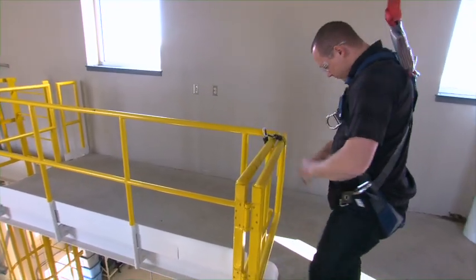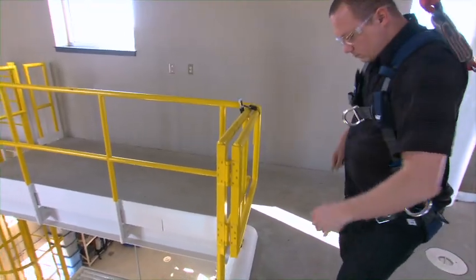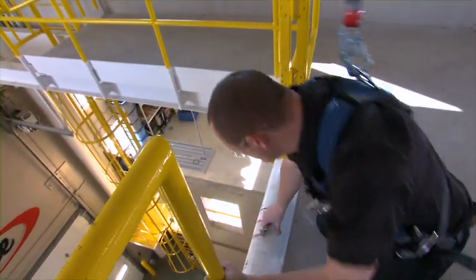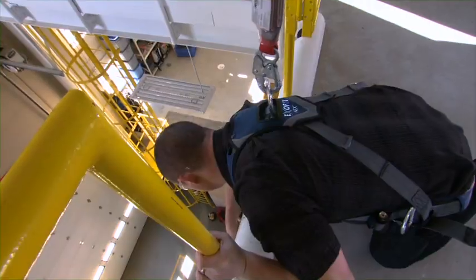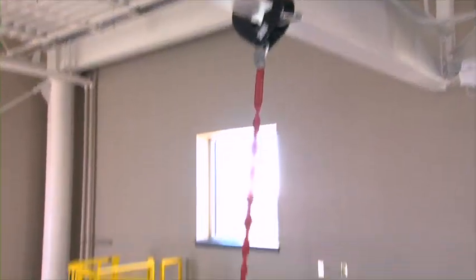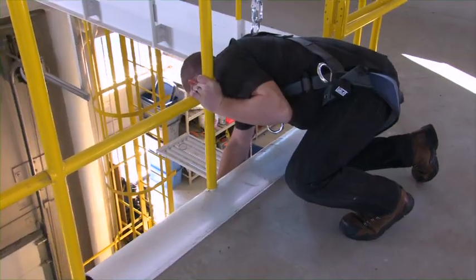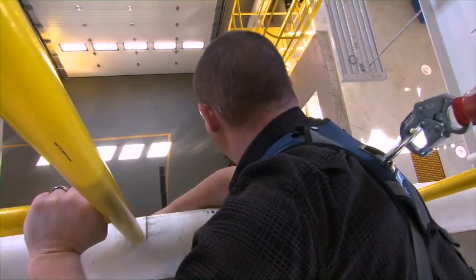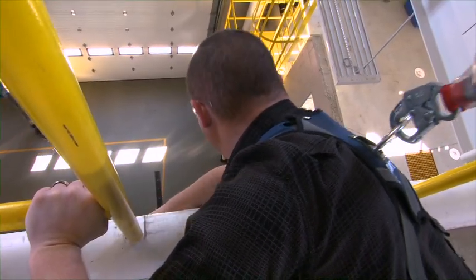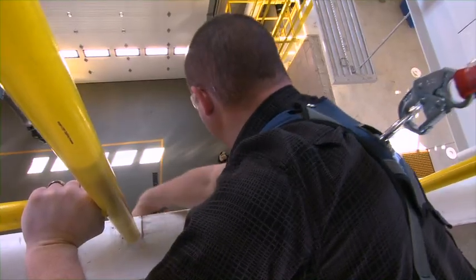Personal fall arrest harnesses have a maximum weight capacity defined by the manufacturer, which includes the person and tools. If there is a need to use a personal fall arrest harness for someone outside the stated capacity, then your employer will need to contact the manufacturer and request a suitable harness. It's as easy as that. It's important to note the requirements prohibit the use of body belts as a part of a personal fall arrest system.